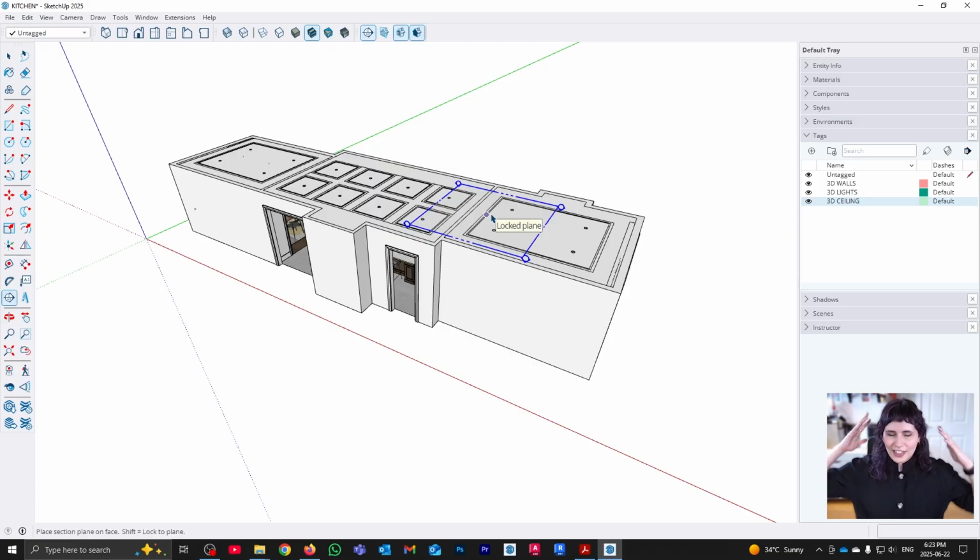So I'm going to start with a top view because I want to create a floor plan. And this is very important to understand: all construction views are sections. It's just that they're in different directions and they have different capacities. A floor plan is a section that is horizontal. Same thing with a ceiling plan. Even an exterior elevation, like a facade elevation, is still a kind of section. It's just that you're cutting outside of the building, but you're cutting through the earth, and that's why you see the earth hatch when you have exterior elevations or facade elevations.